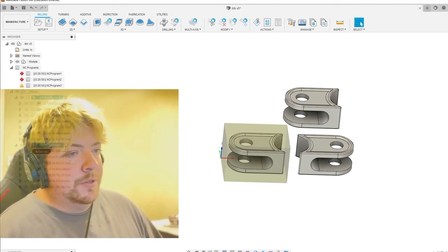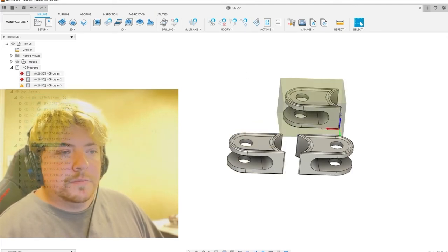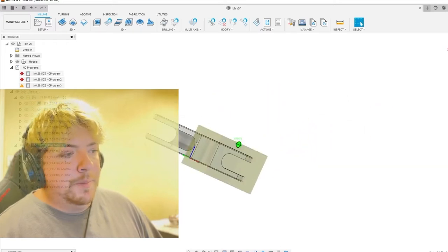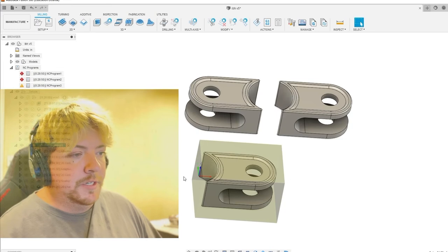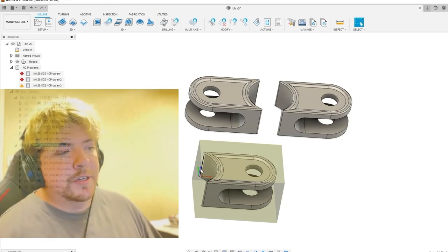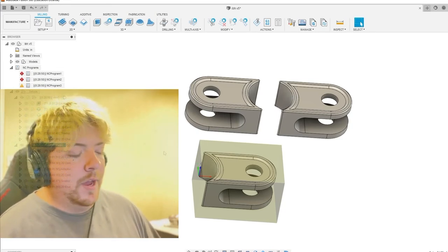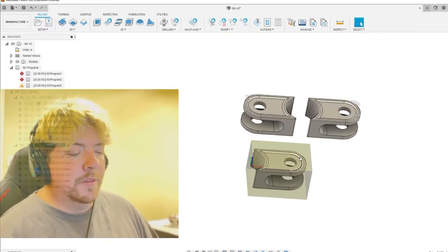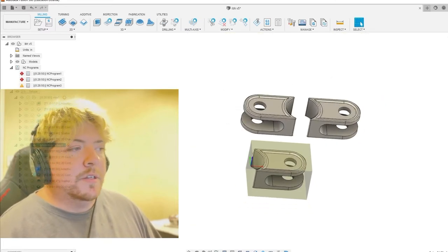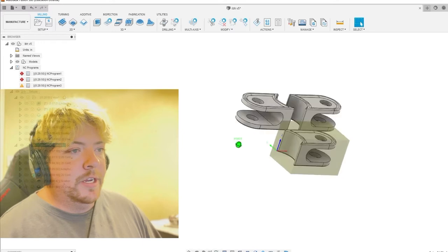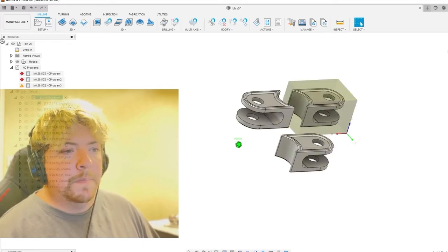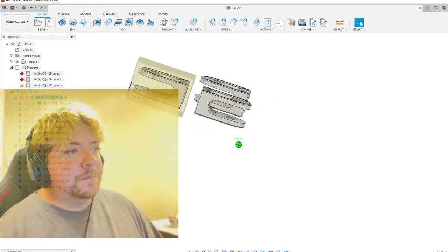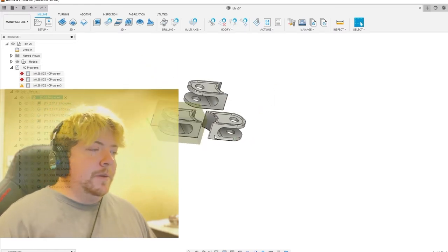And then on setup 2, I'm just going to use the same point on the vise, but usually I'll run 2 vises and have this be a G55 and just set another work coordinate offset for that. And then it'll machine the rest of it. So it's honestly pretty intuitive. I like the way Fusion has it set up. Yeah, so we'll get started here.